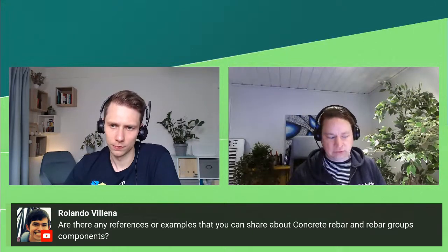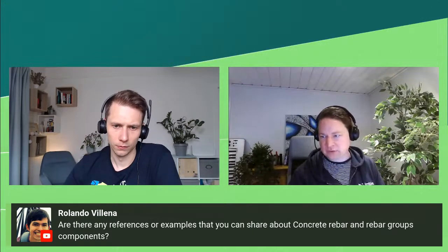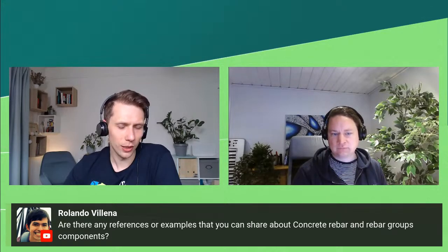Let me see. We have Rolando. Are there any references or examples that you can share about concrete rebar and rebar groups components? Yeah, you should go to the link download page on Tekla Warehouse. There's an example called, I think, reinforcement example definitions, which will generate some different parts with rebar groups in them. This is really a good example for all the rebars. You have tapered, curved reinforcement, and double curved reinforcement. So this is lots of good examples.